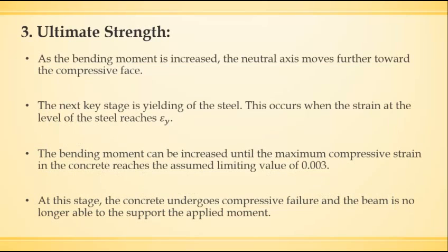As the bending moment is increased further, the neutral axis moves further toward the compression face. This occurs when the strain at the level of the steel reaches epsilon y. The bending moment can be increased until the maximum compressive strain in the concrete reaches the assumed limiting value of 0.003.